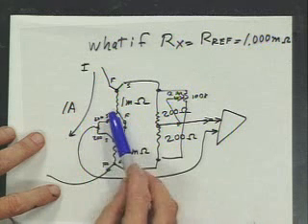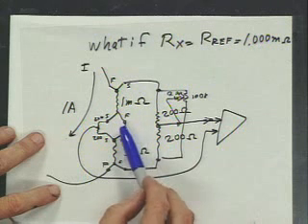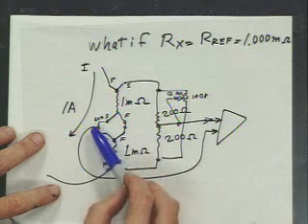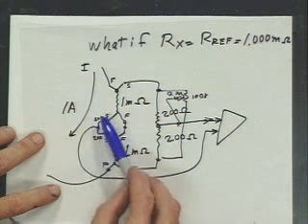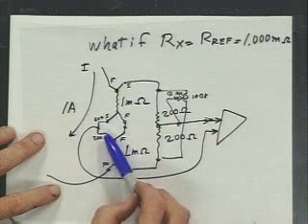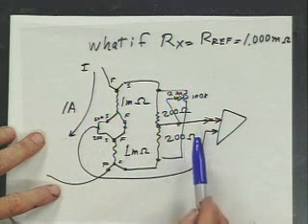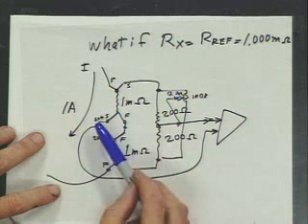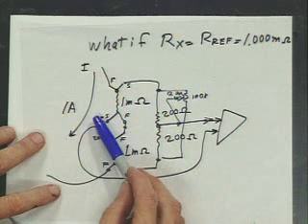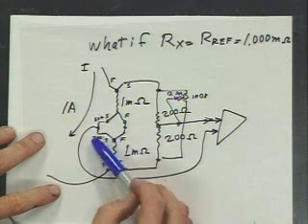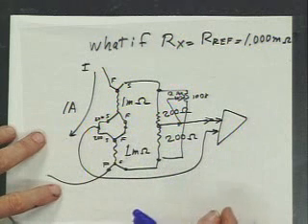So you can't just run this directly. You can't just look at this point. You have to look at the balance point on the sense. This helps you cut down the error considerably to bring that to the error amplifier. But still, that is not perfect. Even when the 200 ohm resistors are perfect, it's not a perfect bridge.